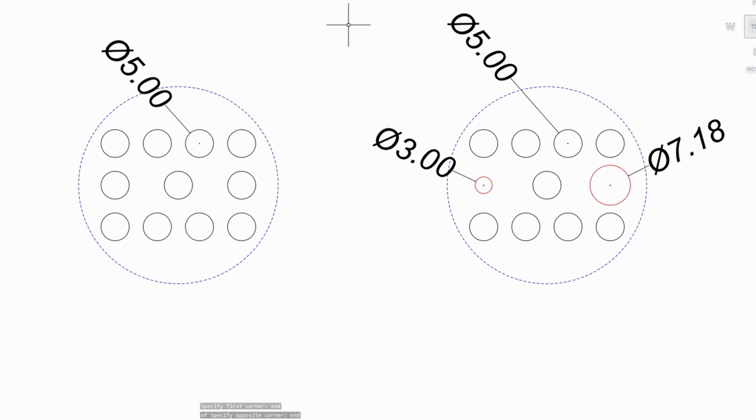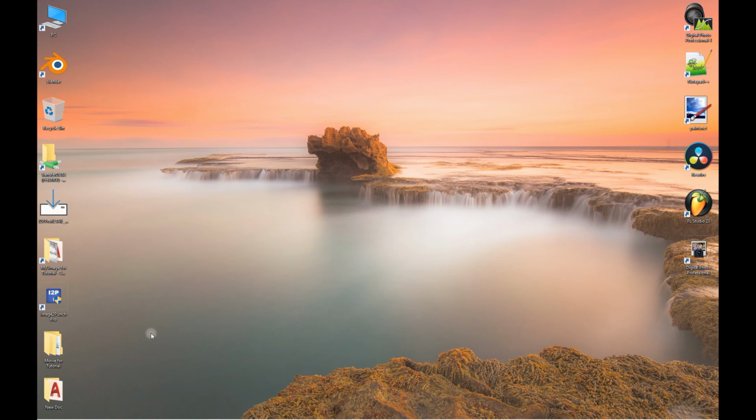Other entities will give an error during the cluster recognition process. As an illustration, this custom cluster tool on the left-hand side is the correct and ideal one. However, the custom cluster tool on the right-hand side is not suitable for cluster recognition as it has two different circle sizes. Now, let's run Image2Punch and import the DXF for the new custom tool.